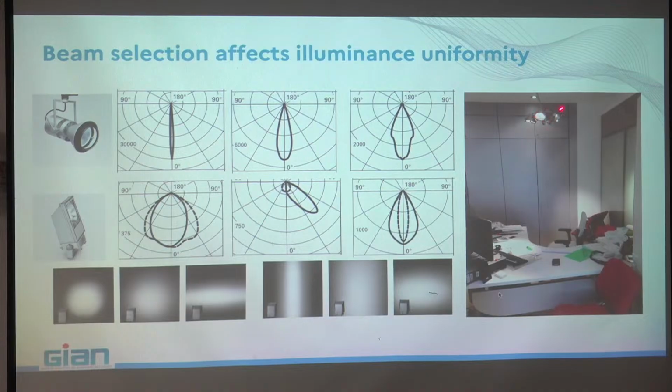It depends on how you choose the luminaires above, and what you have to know is that many lighting standards impose 80% uniformity on the desk. That means here I don't have 80% uniformity on the desk. I have more than 20% more light here than there, otherwise I cannot observe it. And this means the choice of my fixtures above, most probably, is not compatible with the lighting standard. It's not a good choice.